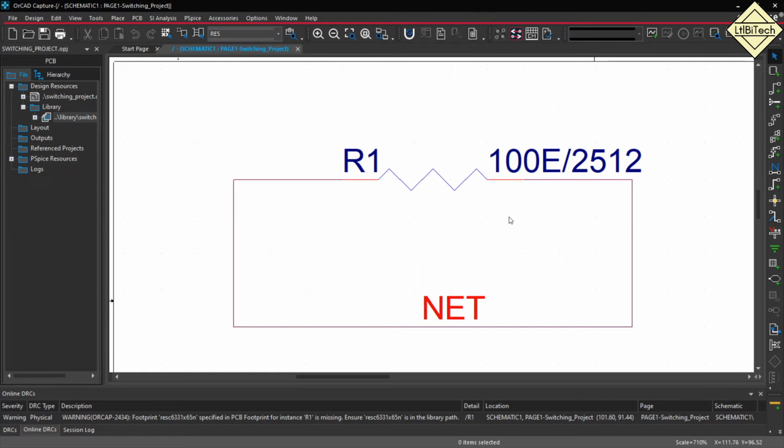Now we will discuss switching from schematic to PCB board design. So we have performed the schematic preparation. We have downloaded the footprints, we have attached the 3D model to the footprint, and also we have cross-checked pin to pad matching. So everything is fine. Now we will discuss switching. Before going to switching, we will understand how it works. So first thing we did is we prepared a schematic.